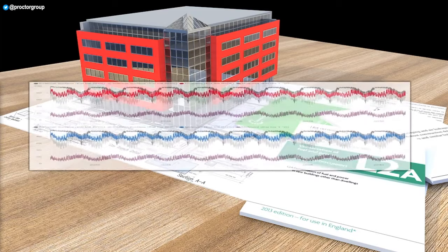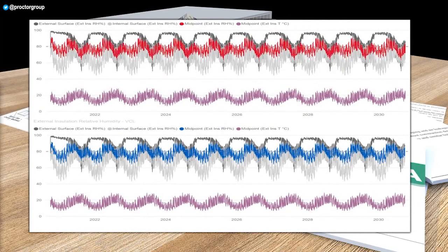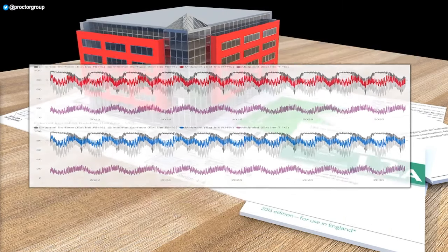In addition to fully modelling the energy performance, we must also make sure we properly assess how the building design balances moisture. Balance in this context meaning we must ensure that all moisture associated with the building can dry out, and that any moisture accumulation or wetting is balanced and equalled during the life of the building.